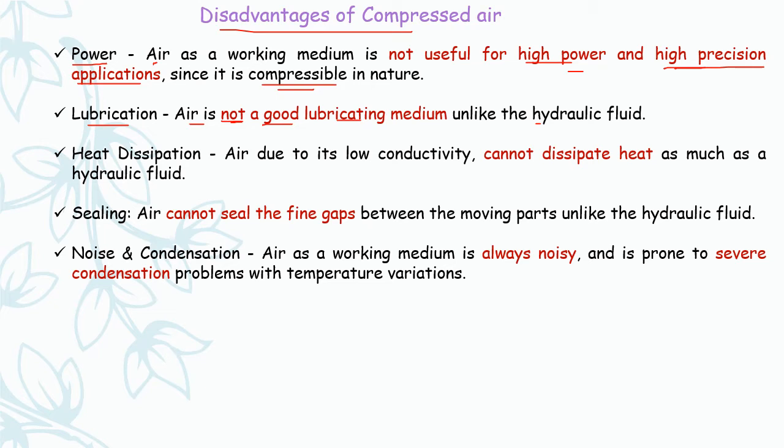So next disadvantage is regarding heat dissipation. Air, due to its low conductivity, cannot dissipate heat as much as a hydraulic fluid. So due to the low conductivity of air, dissipation of heat is lower for pneumatic systems when you compare it with hydraulic systems. So next disadvantage is sealing.